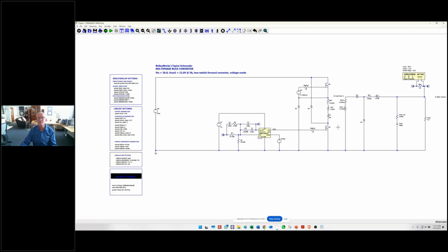This is so much fun to do. I'm having such a blast inside LTspice, putting these new parasitics in there and sweeping the loop. If I had to analyze this from scratch, no, I'm not going to do that. Okay, but yeah, anybody that's got our software, just take these LTspice models, put the proximity in, put the core loss in, put leakage in, put your real FET in there with switching rise and fall times. You'll get the same effect out of that as well. You can move so much closer to the reality than you can get with the equations. So don't get hung up on the equation approach to this.